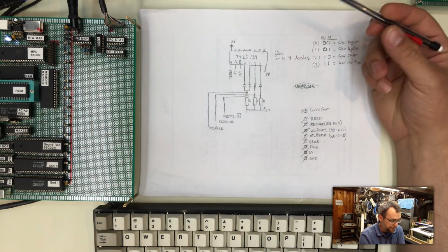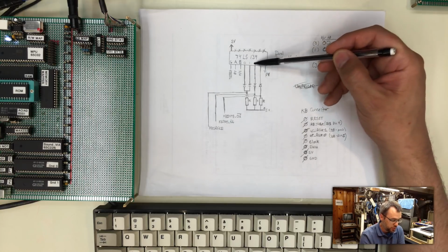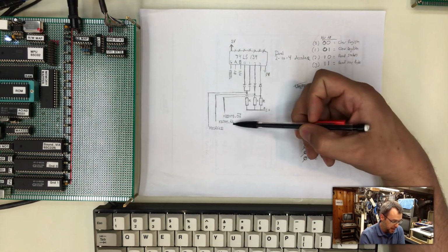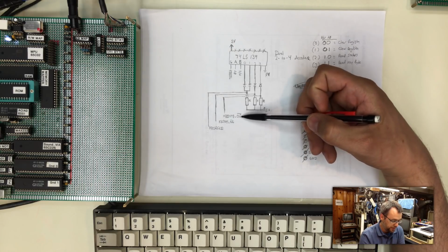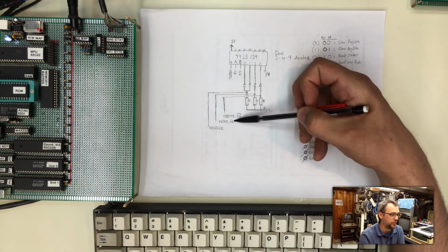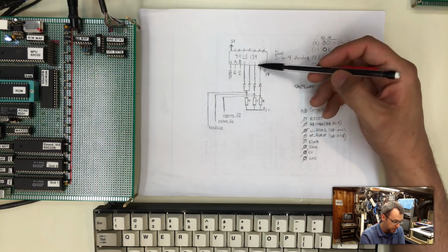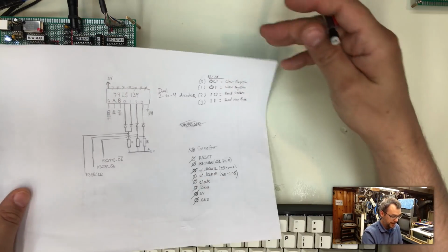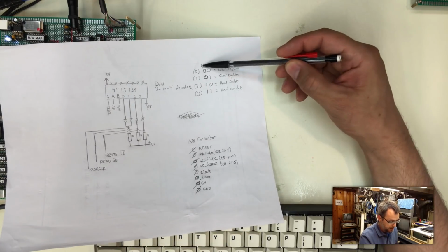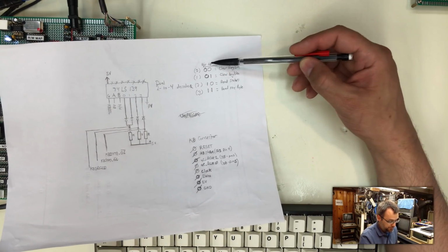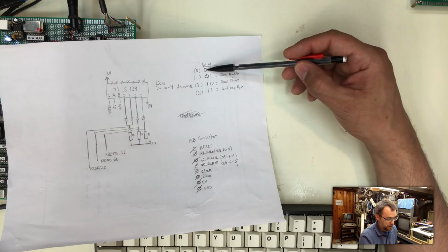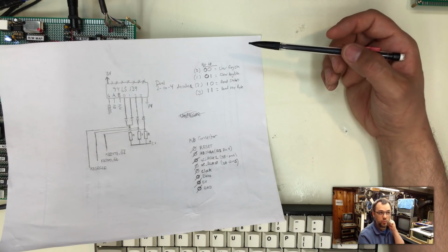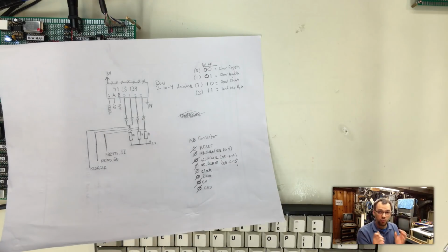The values 2 and 3 that come in on these help me determine whether I'm trying to read the keyboard byte value or the keyboard status value effectively. So when you combine those with that bit structure, as I have written out up here with our RW and A0 lines: if RW is 0, meaning RW is low, that means a write is occurring.